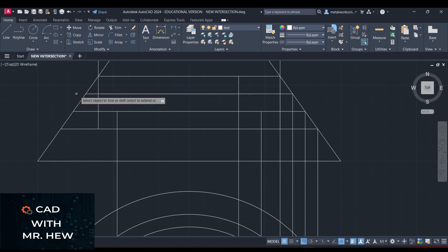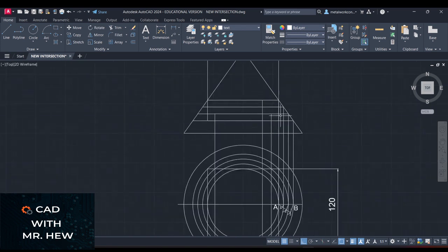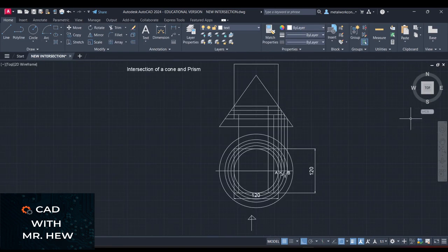As I said, if we were using the traditional instruments, which would comprise a T-square, two set squares, the 45-degree and the 60-degree set square, compass, pencils and French curve, you would let it stay. But for our AutoCAD, I want to keep it neat. So that line coming up, where this line intersects this line, will be the next point. We're going to do the same thing on the next side.